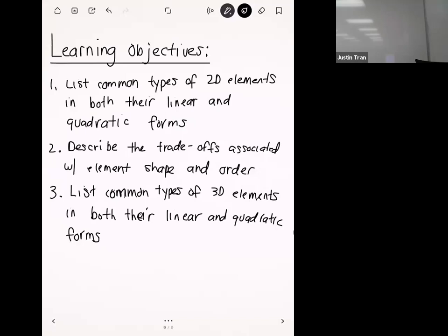It's a good observation, and symmetry is something that's really important for finite elements too. You can basically cut your model in half, and if you have perfectly symmetrical models, then you can get away with just doing half. The important thing is that anything you suppress or cut out of the model, you have to be able to justify.